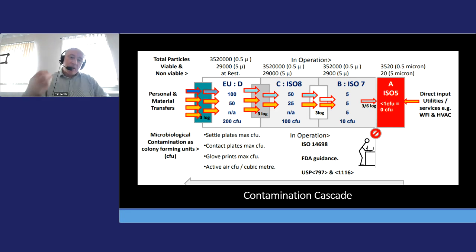But we need to be particularly mindful, as I was saying, in the areas where we've got interconnection between these clean rooms of different grades. So we will have weaker points at intersections, so things like airlocks, be they airlocks for materials, changing rooms, which are effectively airlocks for people, and things like transfer hatches and the like. So there are concerns, and we need to focus on those as the particular points of our zonation concept.